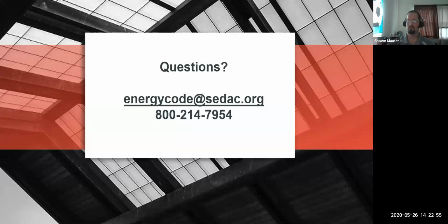All right, we've had a few other questions come in from other sections of the presentation today. One we got here is, how are single tenant renovations that include mechanical system work in multi-story buildings affected by the energy recovery, ventilation, and economizer fault detection and diagnostic requirements? If you're doing individual tenant unit work, usually you're not going to be changing the central exhaust fan or the central HVAC system. And so those would not trigger updates to be in compliance with energy recovery, ventilation, or fault detection and diagnostics.